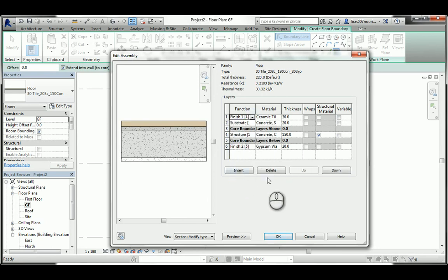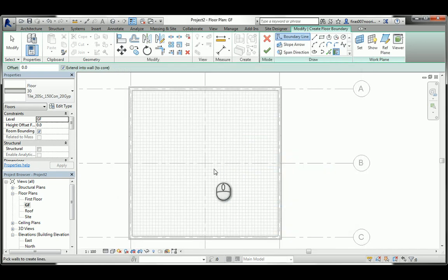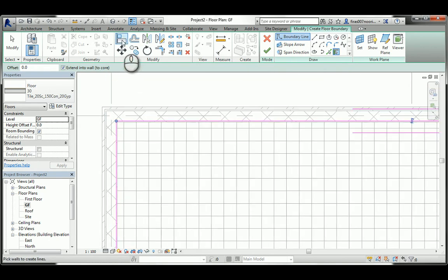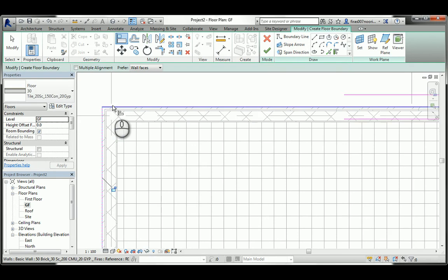And I'm just flipping this. This is an external. That will be air here, while this will be the ground floor. So that's an internal finish. Hit OK. Hit OK again. Again, hover, tab, click, and I will align that to the external. I know it's going to be shown. You might not like it now. It's okay.